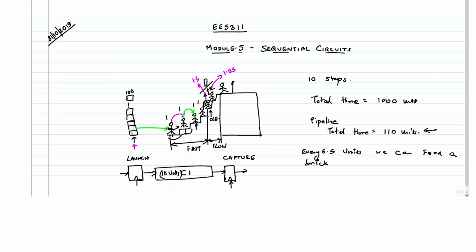If I want to pipeline this just like the way I did there, what I would do is break this guy. It's like each guy now is a logic gate that has a delay, and that's 10 units. Of course, it's partitioned as 1 plus 1 plus 1 plus 1 plus 4 plus 2 plus something maybe. So I'm going to break this down into C11, put another flop in between.